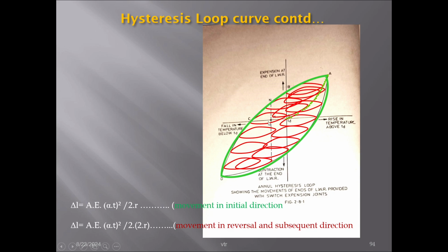Like that, when there is contraction, how much? 10 mm contraction is there for the particular temperature. That means once there is contraction, there will be more gap. So 20 plus 10, that means 30. That means 15 to 30 mm gap. That is the range. So this is what it says. From that we are able to compute, for each and every degree of temperature with reference to TD, how much gap should be there, and based on that we can compute and table them.